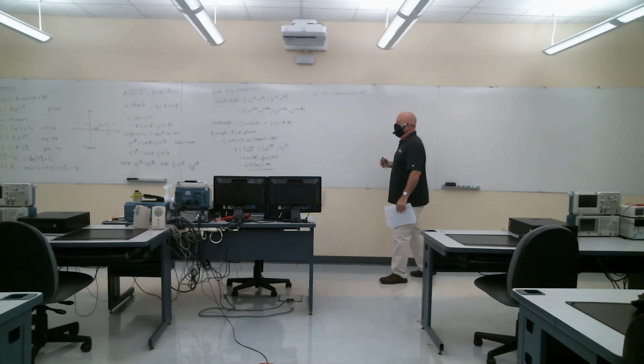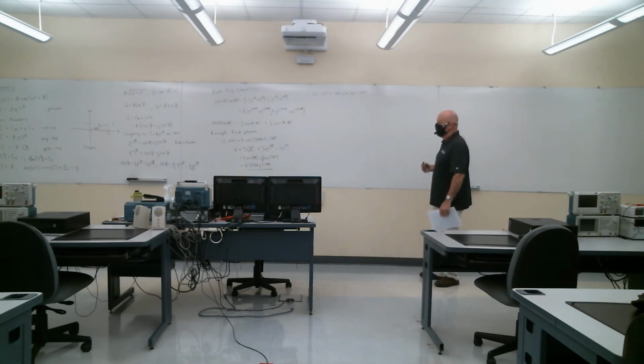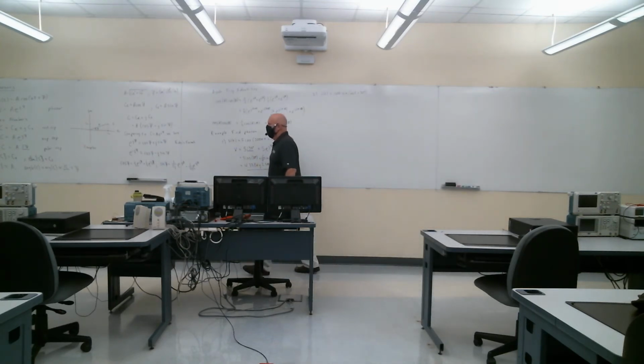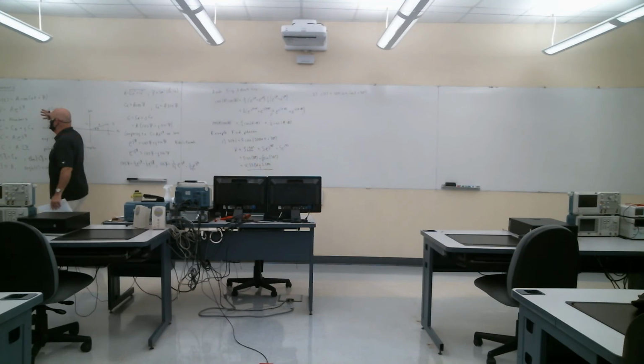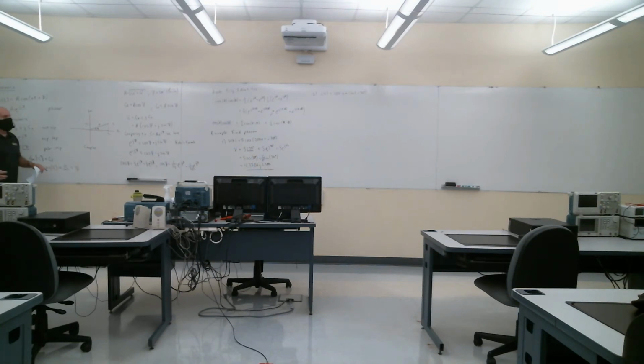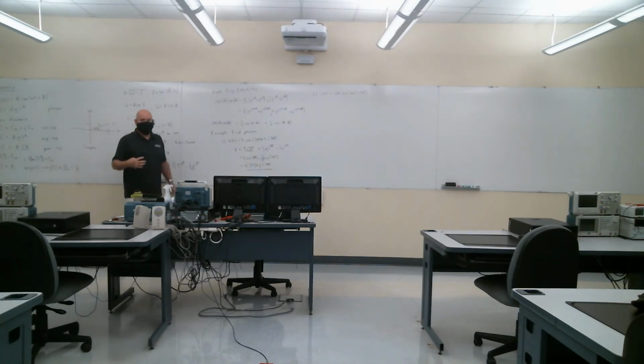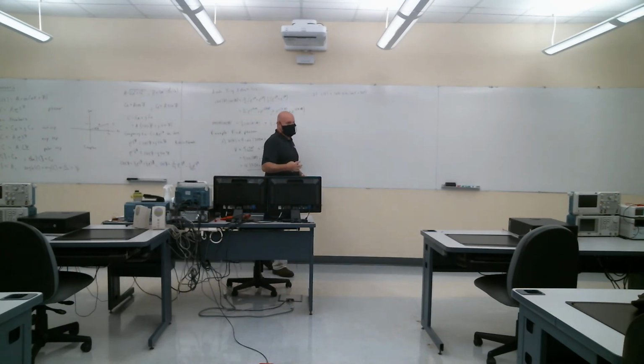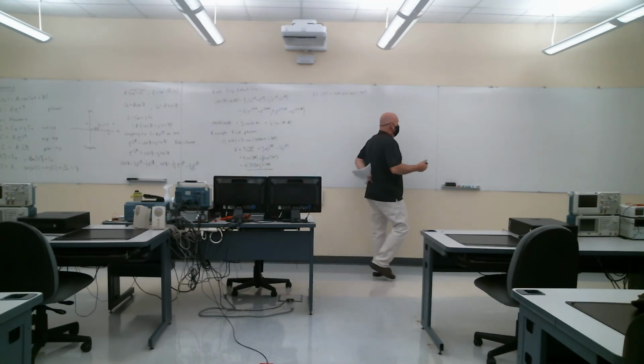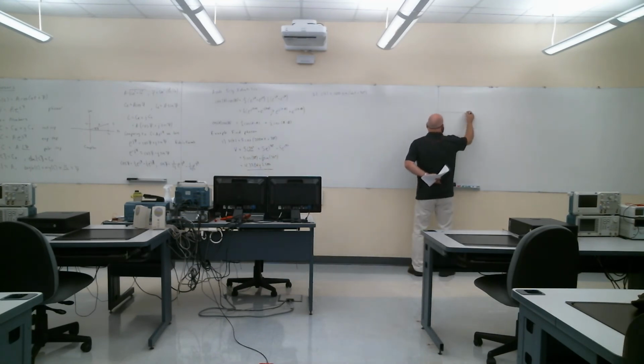Now here you have to be a little careful, because in this conversion from sinusoidal form to phasor form, our reference sinusoid, and it's a convention, is a cosine. Okay. So here we have a sine. We have to convert the sine to a cosine. Now again, you could refer to a book of trig identities. I just mentally picture what the cosine looks like, right?